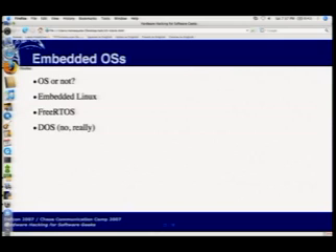That way you can ensure that everything's going to happen on time. For more complicated things, you might have things running on timers where a task only executes every 100 milliseconds, and each task may have an individual timer, or they may all share a single time base where every 5 milliseconds this occurs, every 100 milliseconds this occurs, and you just set flags for when those deadlines have passed.